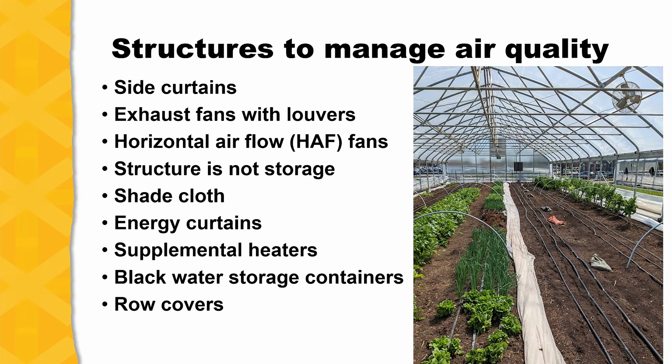Sometimes they're automated based on sensors. You have the exhaust fan here with the louvers. We have the horizontal airflow fan, the HAF fans. One thing that I'm going to show you later, notice that this girl is not using this high tunnel to store stuff. When you put stuff here to store, that's going to prevent proper airflow, right?